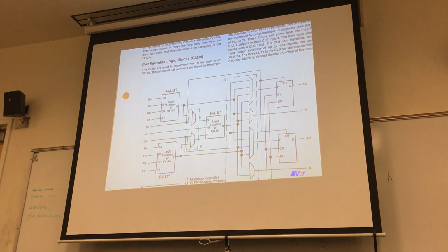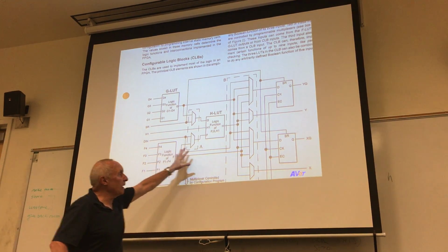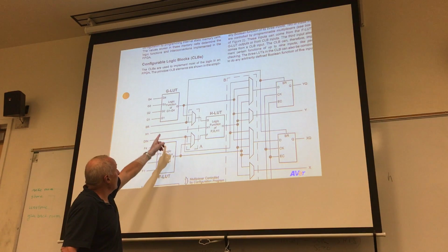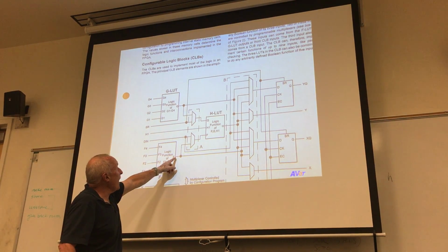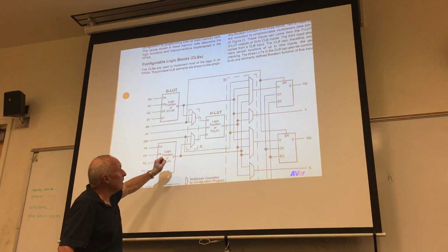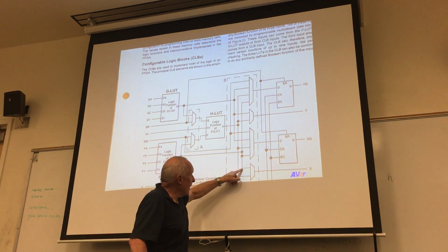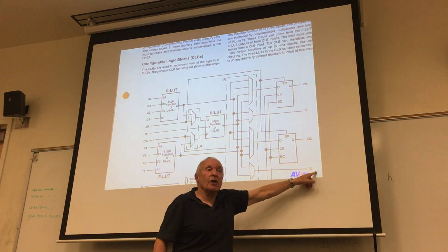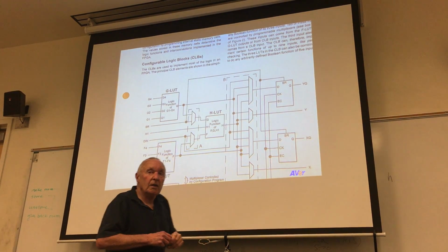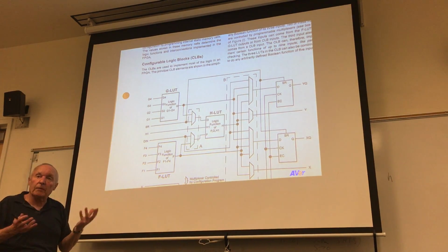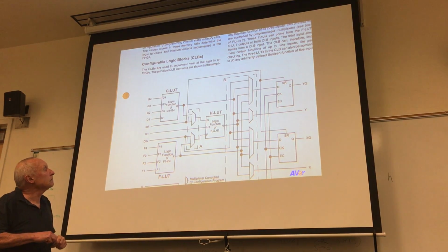So you do have the capability of going from a LUT into the registers and getting a registered output. If I trace the F LUT, and if I choose this upper input, I can get a combinational output from this configurable logic block. So you can get combinational outputs, you can get registered outputs, depending on how you program the multiplexers.